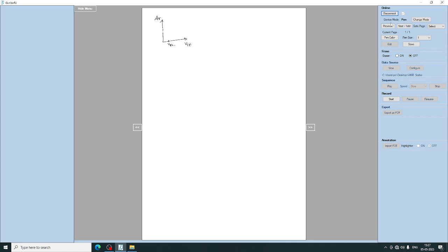Up till this point the transconductance GM will be equal to 0, and after the threshold voltage the output monotonically increases and so does the gain. It will go like this, and the maximum gain of the source follower is 1. So this is the gain versus input characteristics.